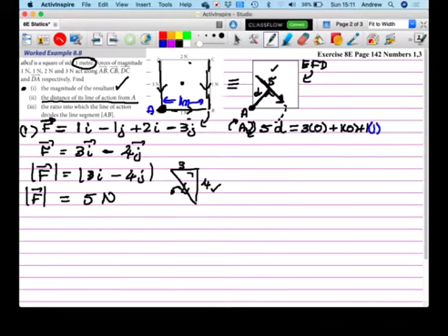And then we've got one more force left, which is the 2 newton force, which is going this way. And again, we're looking at its perpendicular distance. Perpendicular distance is going to be 1 meter. So therefore, is it clockwise? Yes, it is. We can see it is spinning it this way round with respect to A. So it's going to be a plus 2 times 1.